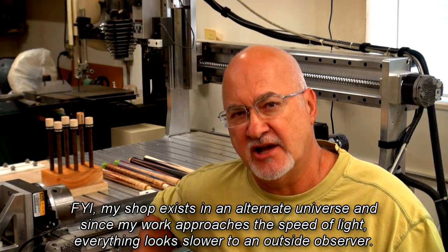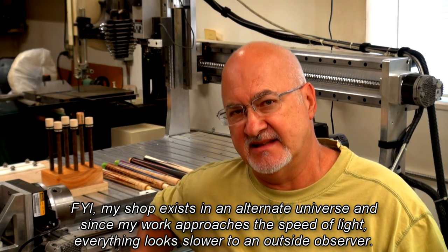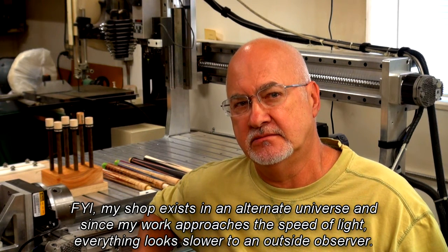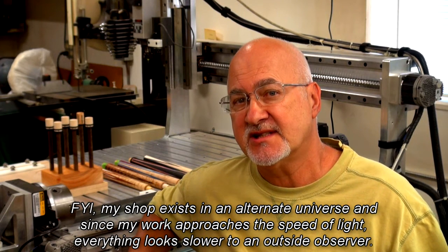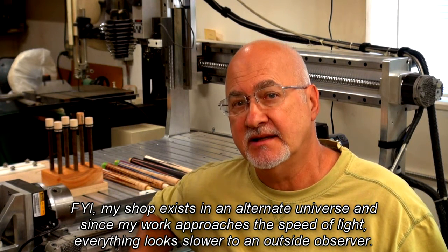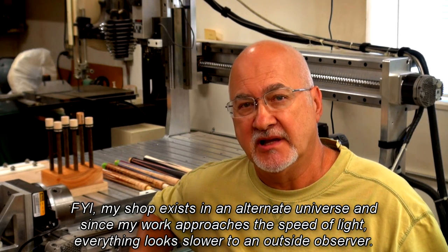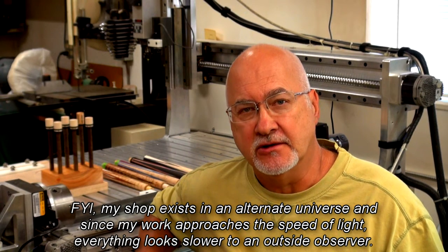Manually cutting the thickness of a slab is no big deal. Everybody watching this can manually jog a cutter over the slab and eyeball the overlap. If it doesn't clean up, you incrementally jog down a 30-second or so and try it again. When one side is finished, you flip it over and wing it again. This works great until you accidentally rapid down in Z instead of stepping down. Talk about a wake-up call.